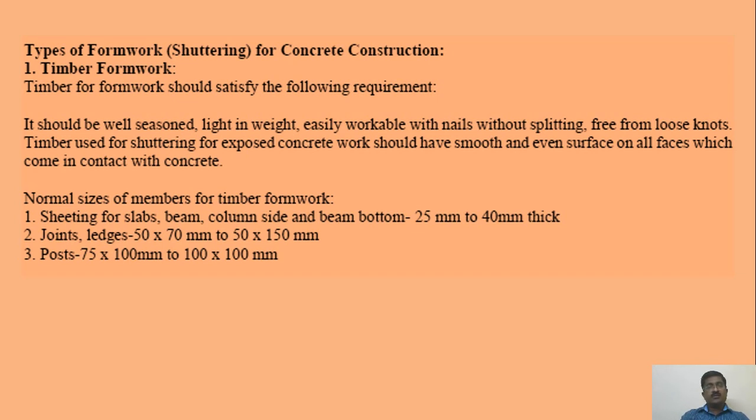First one is the timber formwork. Timber for formwork should satisfy the following requirements. It should be well seasoned, light in weight, easily workable with nails without splitting, and free from loose knots. Timber used for shuttering for exposed concrete work should have a smooth and even surface on all faces which come in contact with concrete.